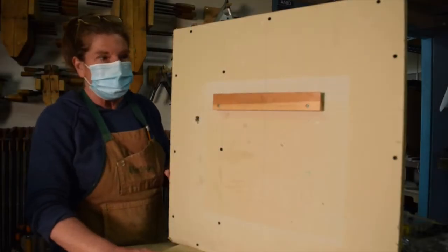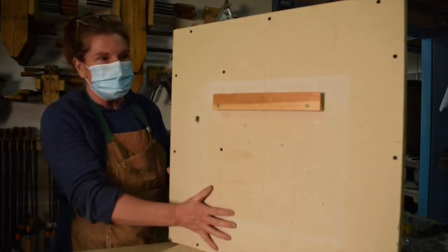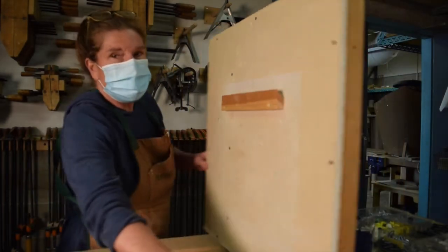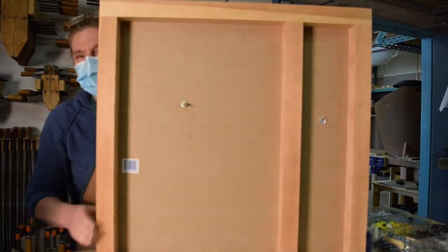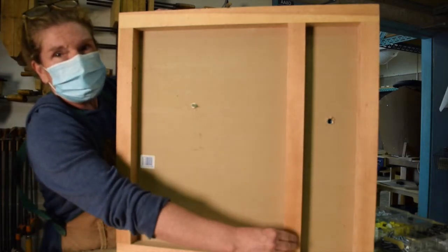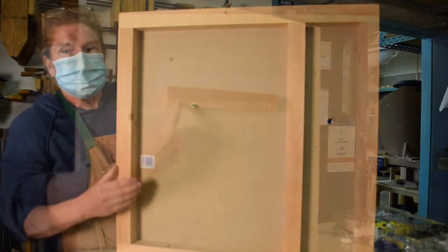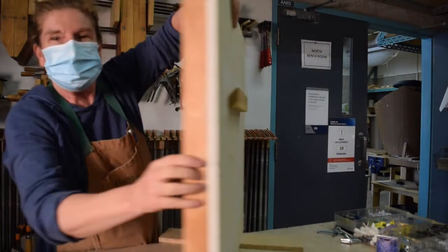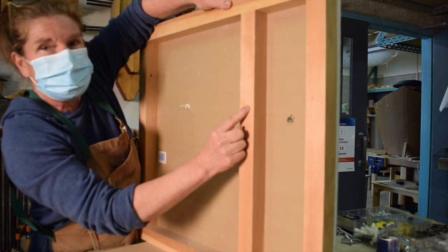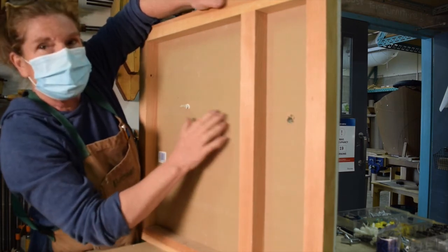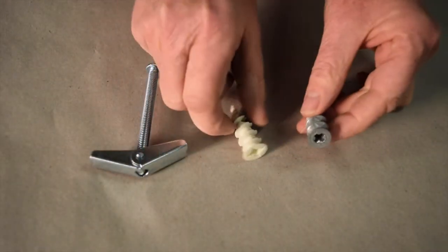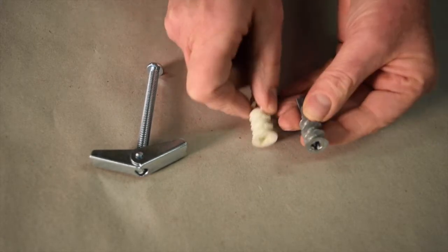Let's start by looking at how we attach to drywall. I've got a sample here of drywall that's attached to a frame that simulates stick frame construction. The studs on stick frames are typically 16 inches apart on their centers. So the cleat that I have attached on the front can be attached directly into one of the studs, which is ideal, but the other screw is going to have to go into the drywall. This is what we use for attaching into drywall.